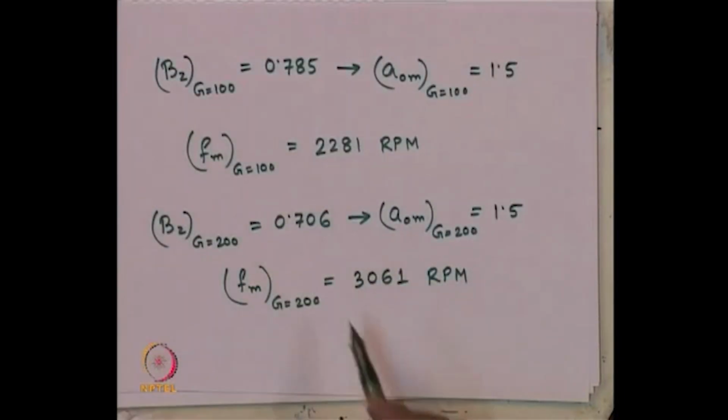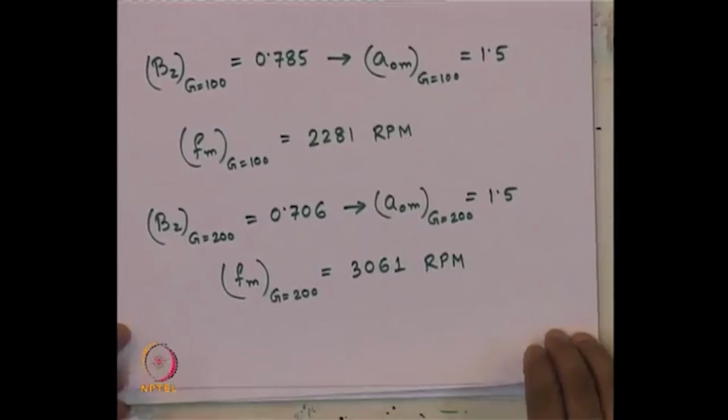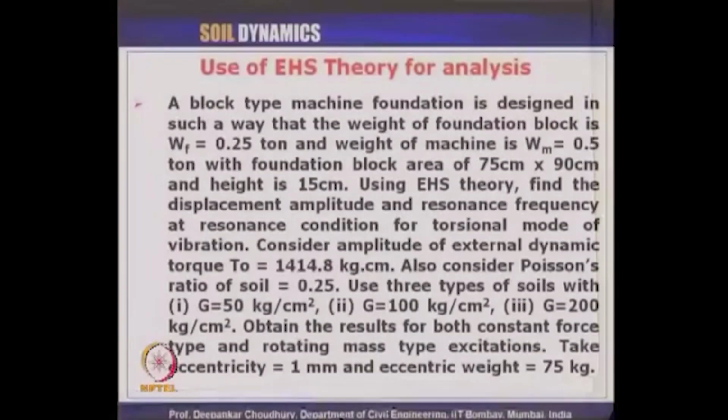However, for the other two types of soil, it is pretty okay, because resonant frequency is far from the operating frequency. So, these are the conclusions or design guidelines that we can propose from these calculations. Now, let us come to the next problem.